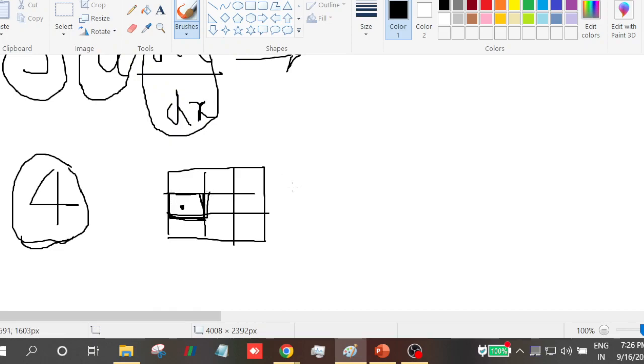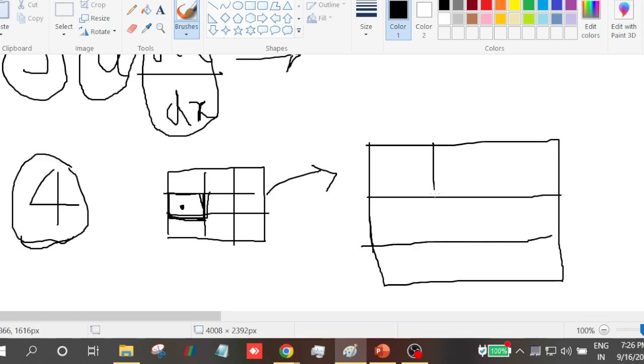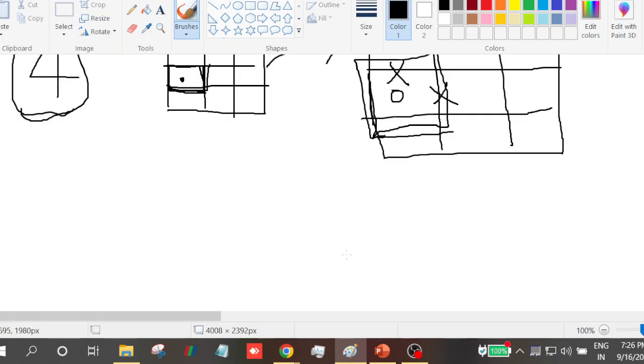Okay, so in order to avoid this, we have come up with a different type of grid arrangement, which is called staggered grid arrangement, wherein we locate pressure at the center of the control volume, but we locate the x velocity at, say, the east face, and we locate the y velocity v at the north face of this control volume. In that way we were able to avoid the pressure velocity decoupling problem. Okay, so let us begin with the tutorial problems.